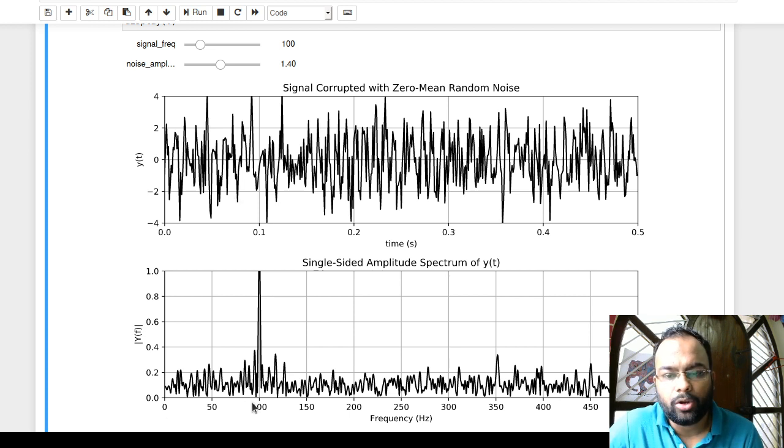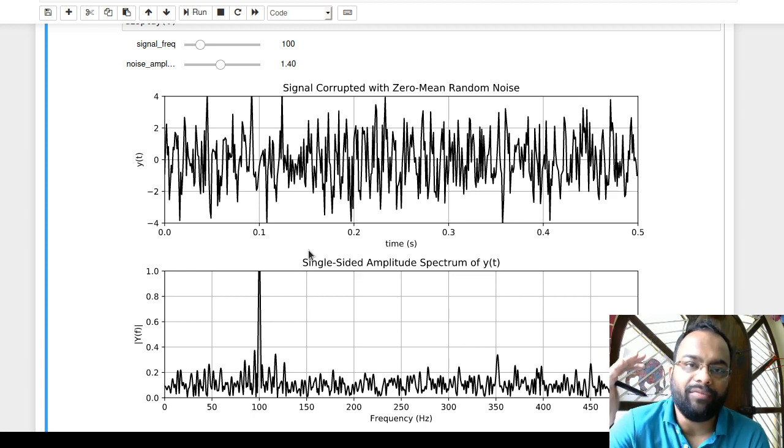And again, look at the peak of the Fourier transform. That essentially tells you that this signal has an internal composition of many different sinusoids which appeared because of the noise we introduced. But inherently, this signal has a pure sinusoid at 100 Hz, and that has an amplitude of about 1. That is what it tells me. So with that said, if I can design a filter that filters out everything other than that particular frequency, I will get to see that particular signal. So that is how, in order to design filters, we actually use the Fourier transform once again.